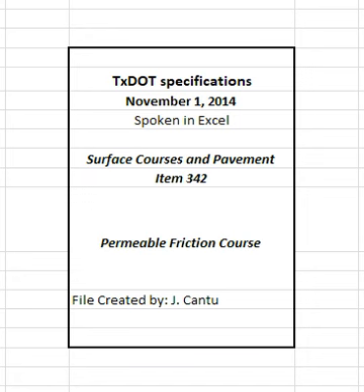2.6.1 RAP. RAP is salvaged, milled, pulverized, broken, or crushed asphalt pavement. Crush or break RAP so that 100% of the particles pass the 2 inch sieve. Fractionated RAP is defined as 2 or more RAP stockpiles, divided into coarse and fine fractions. Use of contractor-owned RAP, including HMA plant waste, is permitted unless otherwise shown on the plans.